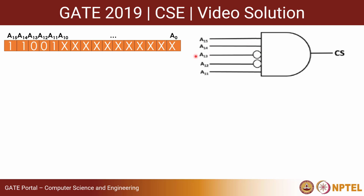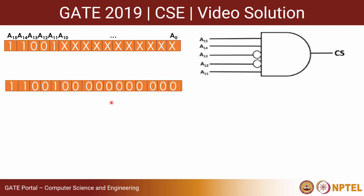A14 is 1. A13 you have to send 0 such that this NOT gate, this is a NOT gate, complemented input, gives 1. So if you give 0, then this AND gate will give me 1. Since this is an AND gate, all these address lines should be 1. A15, A14 is 1. A13 should be 0 so that the complement is 1. A12 should be 0 so that the complement is 1. A11 should be 1. So I have written it in this form. So replacing A10 to A0 with all zeros gives me the first answer, which is C800.